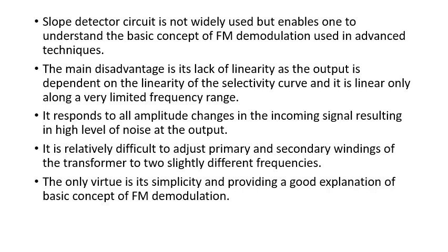If due to some noise or stray fluctuations there are fluctuations in the amplitude of the FM signal, which actually should be perfectly constant, the slope detector circuit does not distinguish them, and the circuit responds to these variations or noises.